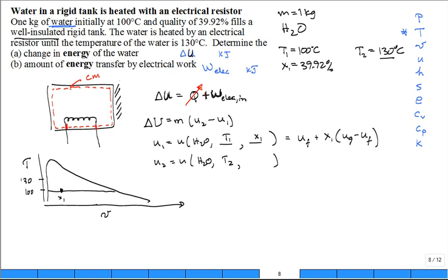And you were helping me, right? Yeah, you were. So why did you say, I can get V2? Because he solved enough of these problems already and he knows some of the patterns. When you have a rigid tank, the volume's not going to change and the mass isn't changing. The ratio of the volume and the mass, you conclude V2 is equal to V1 with a little logic. Rigid tank. True? All right, so you can find V2, that's equal to V1.